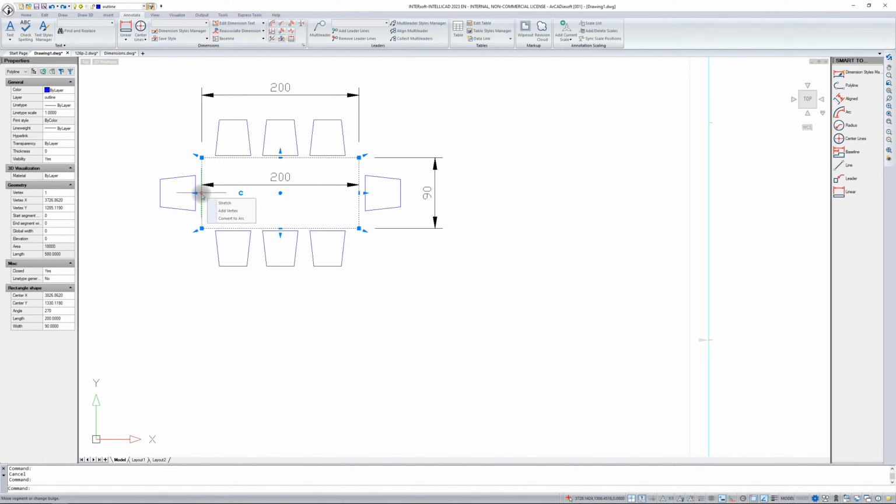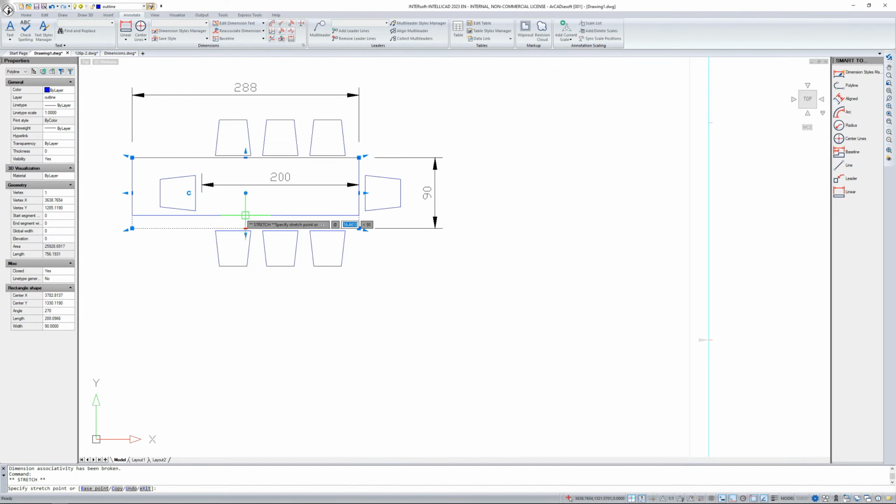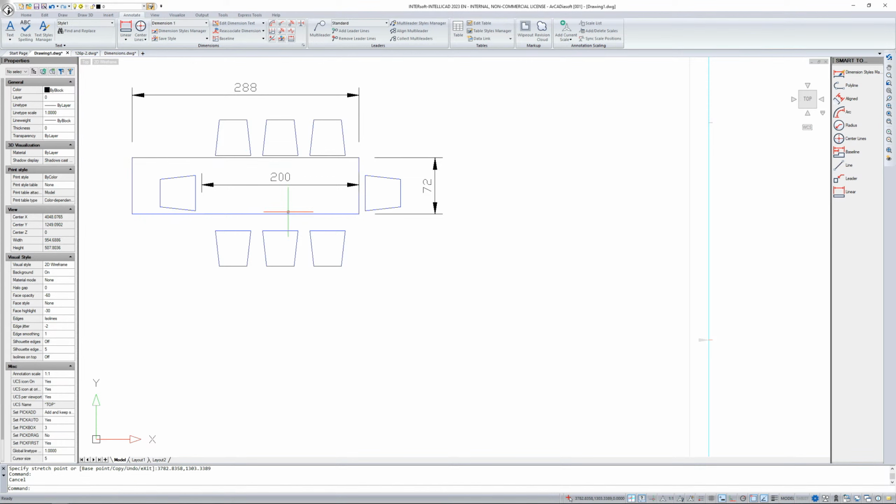The point is that if I modify such a dimension element, then of course the dimension automatically follows this element. So these are the so-called related dimensions. If I want to enter unrelated dimensions, I can modify the value of the variable that now assigns these dimensions to elements. But before I do that, I'm going to detach one of these dimensions from the element. Sometimes you want them to be assigned to elements because you're modifying now, and you don't need to modify this dimension later.